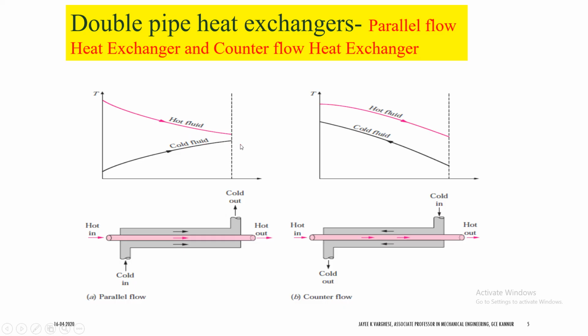So on the other hand, in the case of the counterflow heat exchanger, the direction of flow for hot fluid will be the same because it enters at a high temperature at its inlet, and leaves at a low temperature. The cold fluid enters at its lowest temperature at the opposite end, that is the end at which the hot fluid leaves, and which is getting heated up and exits at a high temperature.